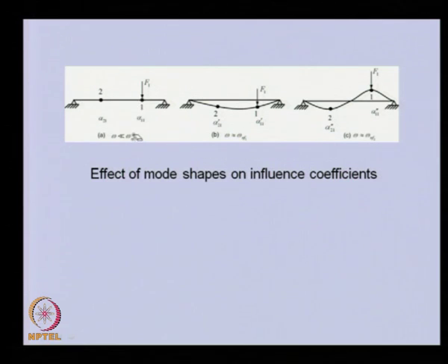This is valid when we operate the rotor much below the critical speed. If we are near the first critical speed, for a simply supported rotor, we expect the shaft to have a deformation like a half sine wave.